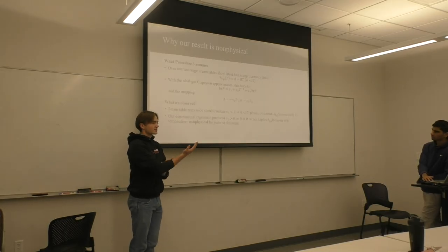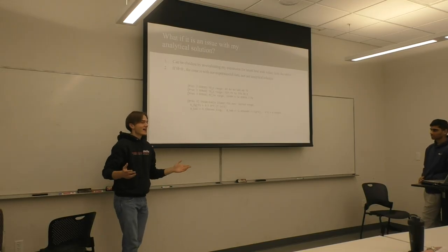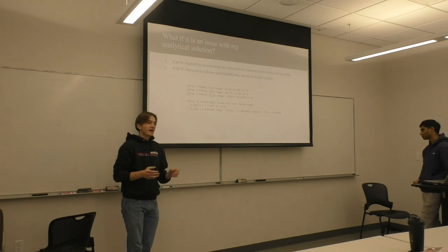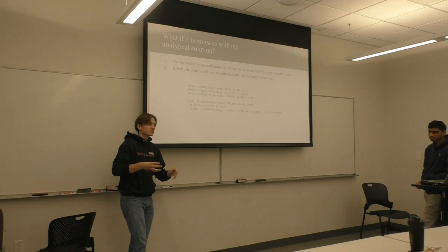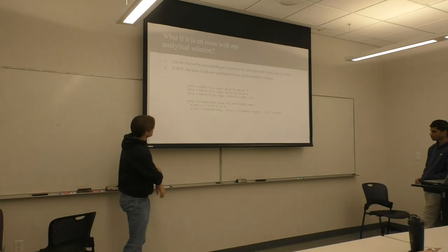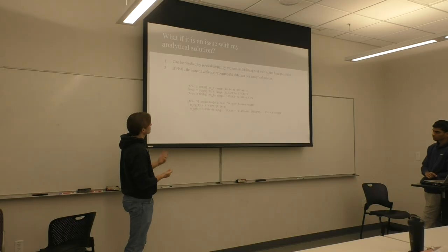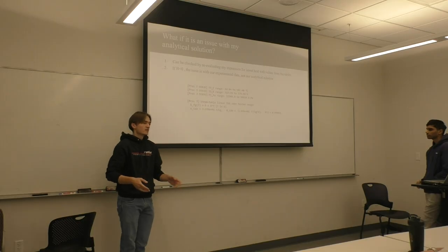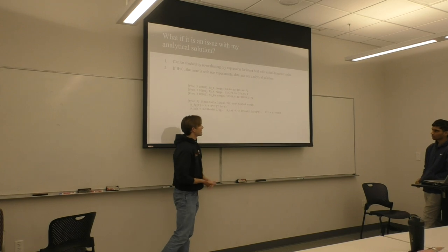That's why it's increasing. So if you go to the next slide, at this point I'm kind of like, all right, did I just do my math wrong? So I checked myself. This can be checked by plugging your data back in, or reevaluating for a different set of data points. If you use the steam table data instead of the measured data that we got, you can run the exact same analytical solution on it. And if it gives you a value of b that's less than 0, that means your analytical solution is correct, but something was wrong with your experiment, or you fed the data in wrong, which is what we find, because when you calculate it, b is a negative value.